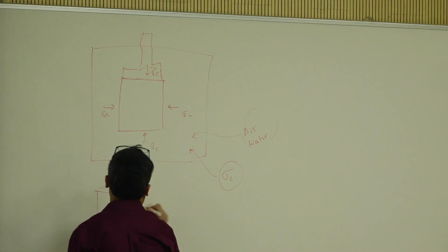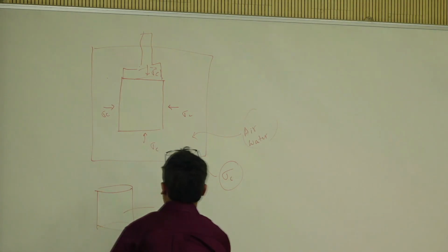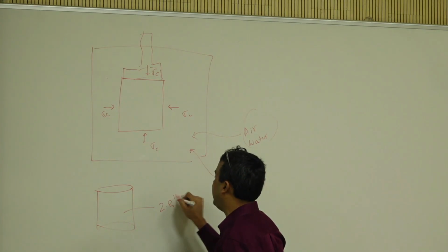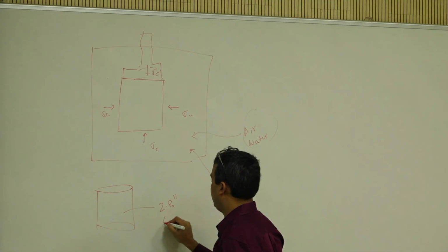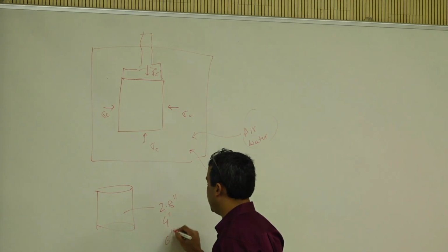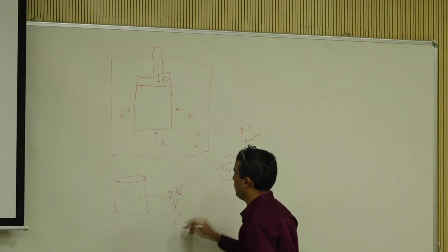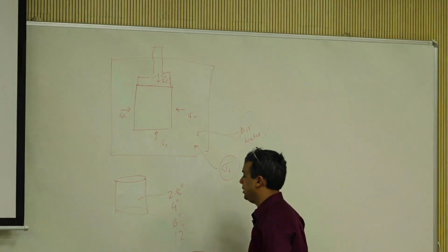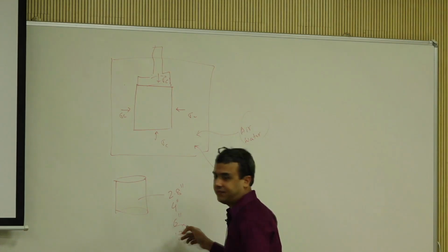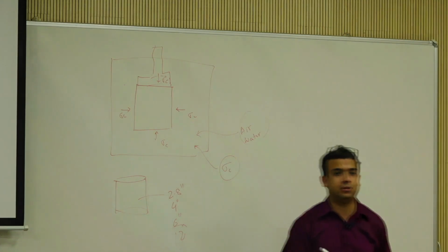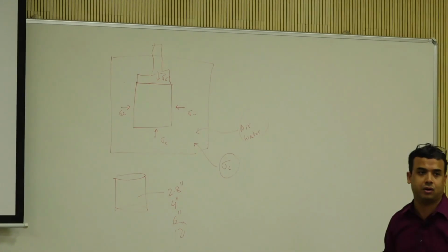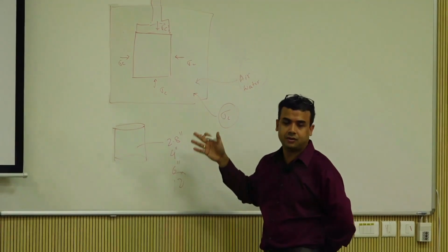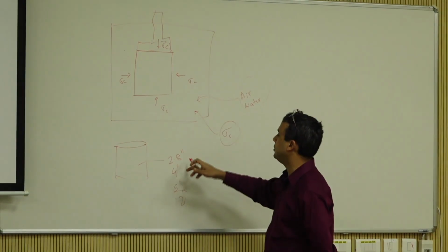If you're working with fine soils, you can have diameters in the range of 2.8 inches, 4 inches, 6 inches, up to 12 inches is what I have tested in my life. So it's 12 by 24, which is like 300 millimeter diameter, 600 millimeter samples. So this is railroad ballast and stuff like that.